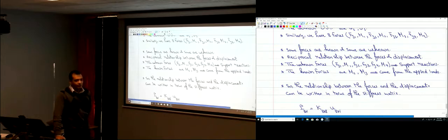At each node, how many degrees of freedom are there? 2 if it's a two-dimensional structure and if it's a beam, but that one is a frame, so you have 3 degrees of freedom at each node if it's two-dimensional. But actually it's three-dimensional, so you have 6 degrees of freedom. So 6 times 400, so the stiffness matrix is 2400 by 2400, okay?